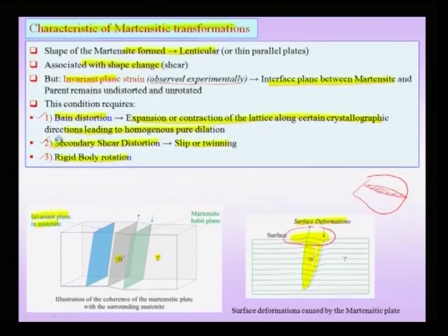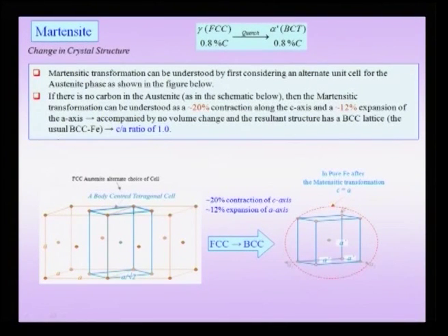So, in the martensitic structure we have the gamma FCC which forms a body centered tetragonal structure, the alpha prime structure, and the composition during this whole process, and we produce martensite typically by quenching. Therefore, as we talked about, if we take water and quench our sample from the austenite region, we can produce martensite, and the composition does not change.